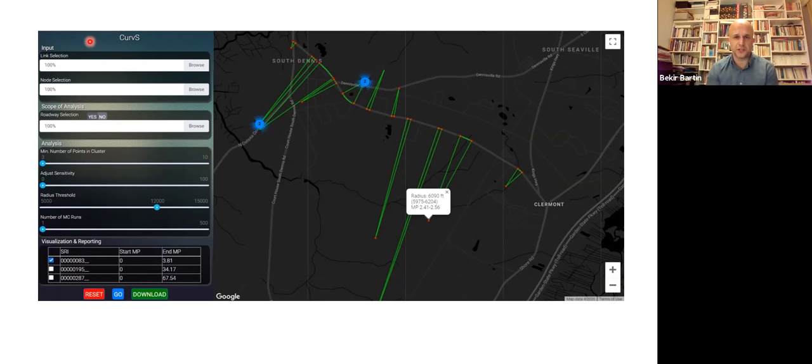We use QGIS, which is a free-of-charge GIS tool. It can be done in ArcMap as well, but it requires manual input. You need to extract the link file and the node file and upload them on the map.